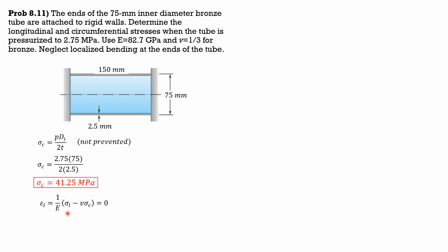So therefore, sigma L equals Poisson's ratio times sigma sub c. So stress longitudinally equals Poisson's ratio times stress circumferentially. So longitudinal stress is one third of 41.25. So longitudinal stress is equal to 13.75 megapascals.